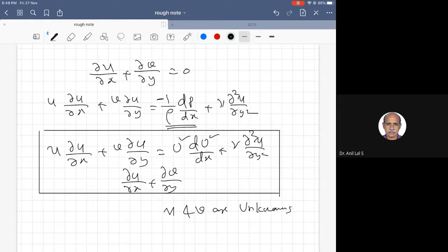So we have studied methods for determining the potential flow velocity distribution over different bodies like circle, ellipse, airfoil, etc. We do that kind of solution for the potential flow velocity distribution, and that is given as an input for solving the Prandtl boundary layer equation. So this has to be solved. This is again a non-linear partial differential equation.